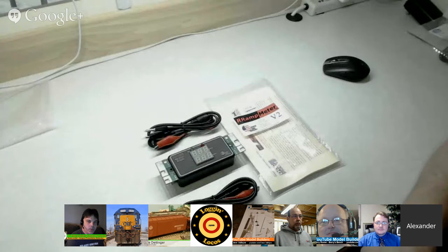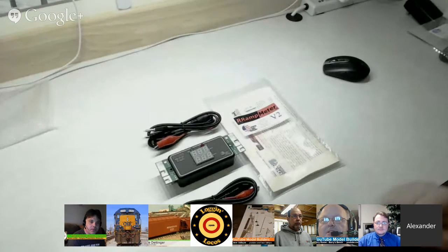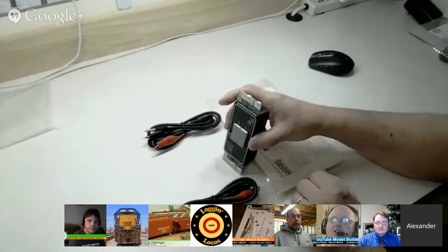One simple law: watts equals volts times amps. 10 watts, no matter whether it's 1 volt at 10 amps or 10 amps at 1 volt, it's still 10 watts. Exactly. And that thing will melt your locomotives too, especially N-scale guys. Listen carefully. The nice thing with the amp meter is you can touch its contacts right to a section of track and it'll tell you how much current is being drawn.